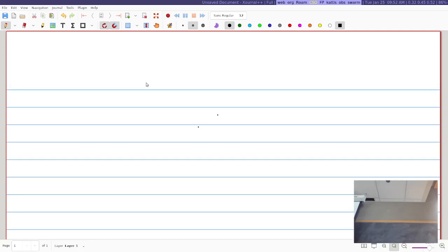If you haven't figured this out already, you're definitely going to be using lots of muxes in your ALU, because that's how you make all these choices. But as Zach was saying, you don't have to think about it in terms of making the choice up front. You do all the things, and then you choose which result you want at the end. When I started the project, I had this complicated thing where I had a demux at the beginning and a mux at the end, and then I realized I don't need that.